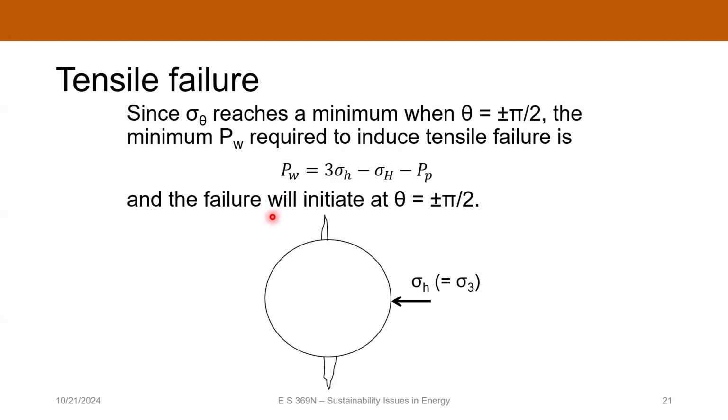This actually, just as a side note, if you're a geomechanics person and you want to know what direction your maximum and minimum horizontal stresses are, you can look at boreholes that have been drilled in the area where you're looking and look for drilling-induced fractures. And you can say, okay, I know that the drilling-induced fracture is in the direction of the maximum horizontal stress. So the minimum horizontal stress is 90 degrees. So that's something you can actually do that's useful with these things. But that's going to be your tensile failure.